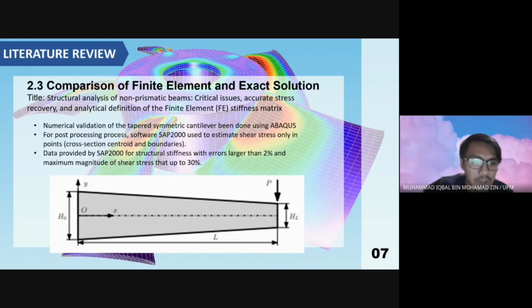For the figure, it focuses on the effects induced by the constraint on the left hand side and load distribution on the right hand side. The distributing coupling constraint has been made using points (0,0) and (0,L) as reference points.